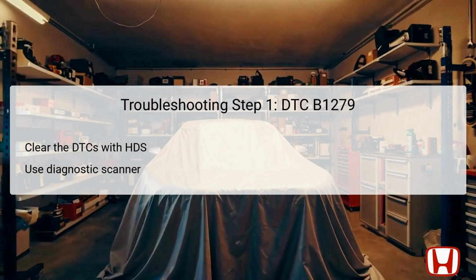After clearing the codes, you need to turn the ignition switch to the lock position and then back to on. This action helps reset the vehicle's electrical systems. This step corrects any temporary glitches in the ignition or electrical circuit that could interfere with accurate diagnostic readings. A successful reset prepares the system for further testing, ensuring that only active faults are evaluated in the subsequent steps.